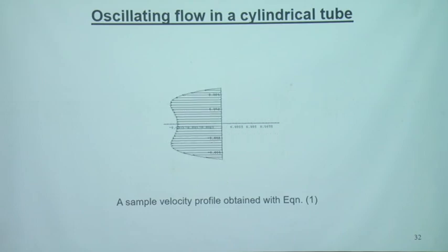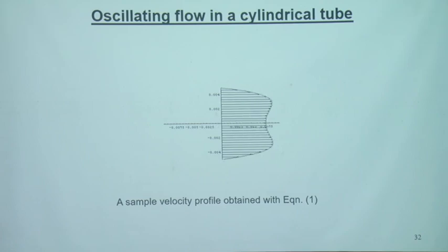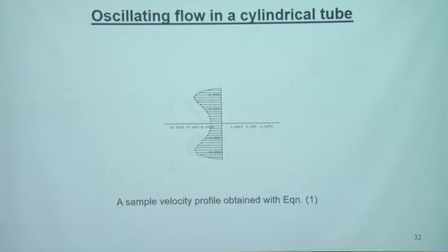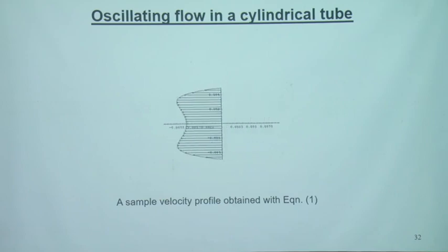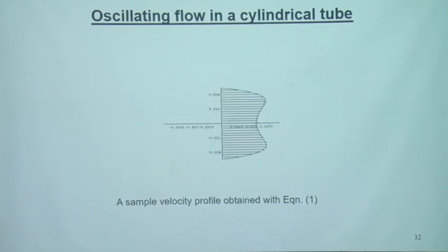So this is how the velocity profile looks visually. You can see that because the pressure gradient is time dependent, it varies over time, so the velocity profile is also a function of time. In terms of the shape of the velocity profiles, it's no longer parabolic. It depends on some dimensionless parameters that we will describe in the next slides. Typically it can have M-shaped or W-shaped velocity profiles. This is just a typical example of the sinusoidal velocity profiles at a particular frequency.